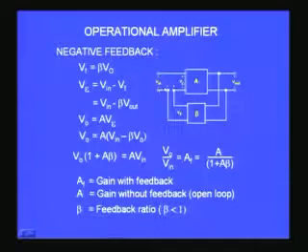This is plus minus and this is minus plus. So when it is given in opposition, what will be the balance that is applied across the terminal? I call it V epsilon, and that is what is actually applied now. So what is Vf? Vf is actually beta times V output. Beta is less than 1, it is a fraction, and therefore a fraction of the output is given